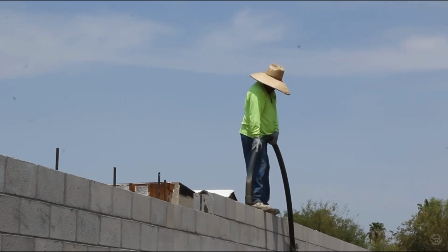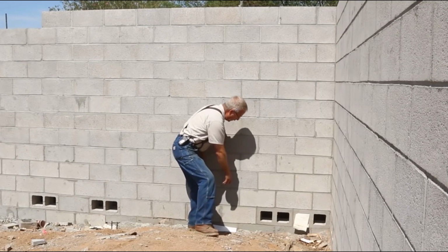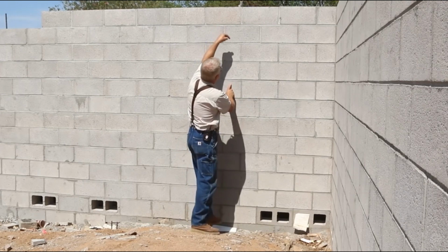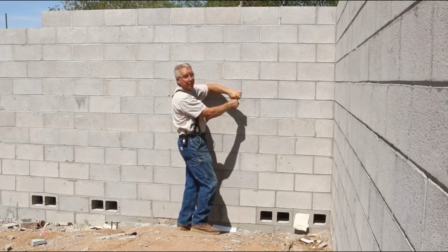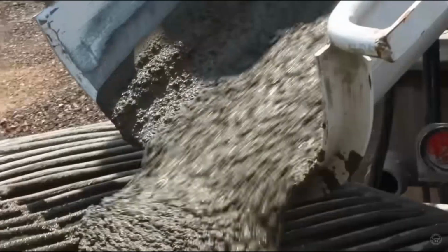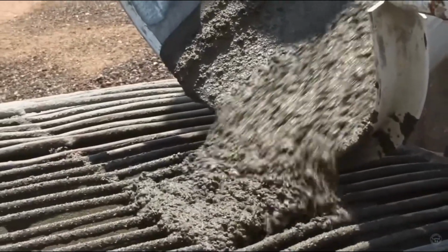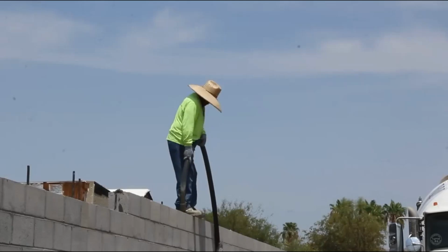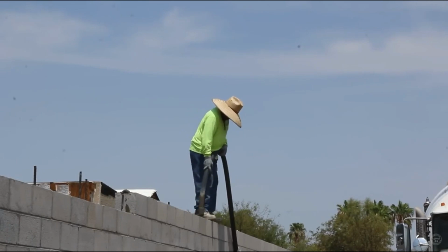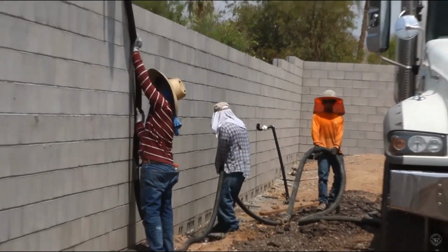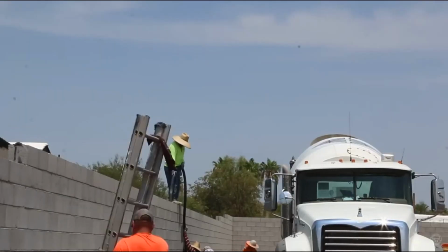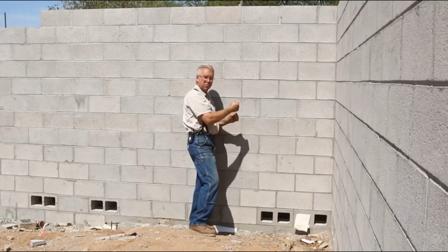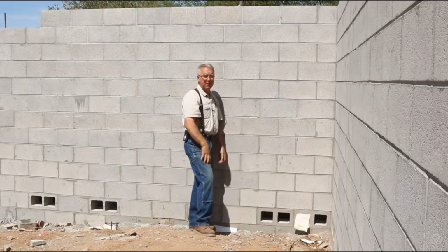There's a rebar vert, number 5 bar, that comes out of the footing, comes up inside the cell. Another vert is dropped down from the top so that they overlap, and then the whole cell is filled with grout. It has 3/8 aggregate in it. Those rocks are gripped in the hydration process and provide a vertical beam. When that gets hard and encases the rebar, it acts as a very, very strong spot on this wall to resist any bowing or bending or overturning.